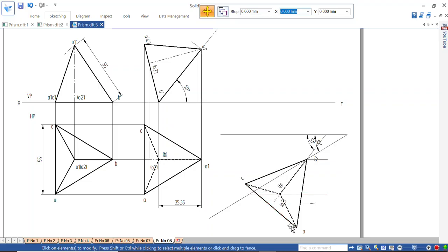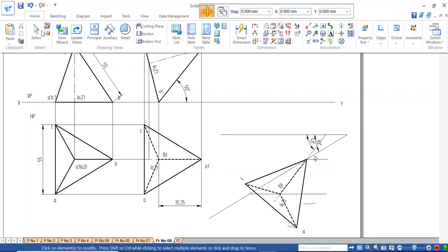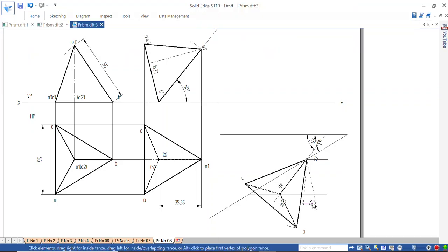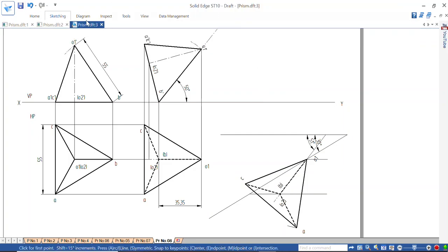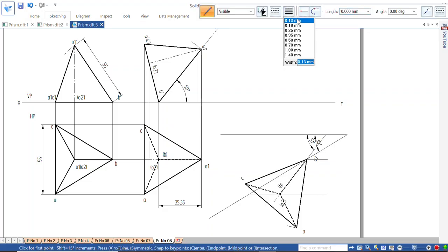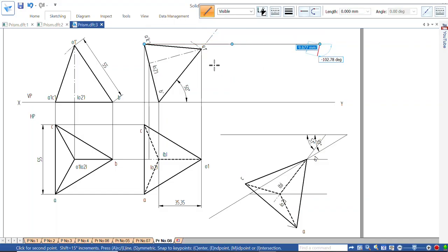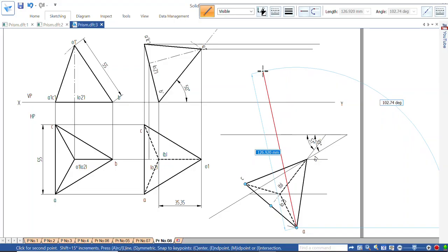Okay, these arcs are disturbed because of rotating. Later you can delete these unwanted extra arcs. Now project upwards with thin line to draw the front view. Thin line, project this first towards the right side. There is the apex point and E point. Okay, and B is on the XY line only. A and C, O1.